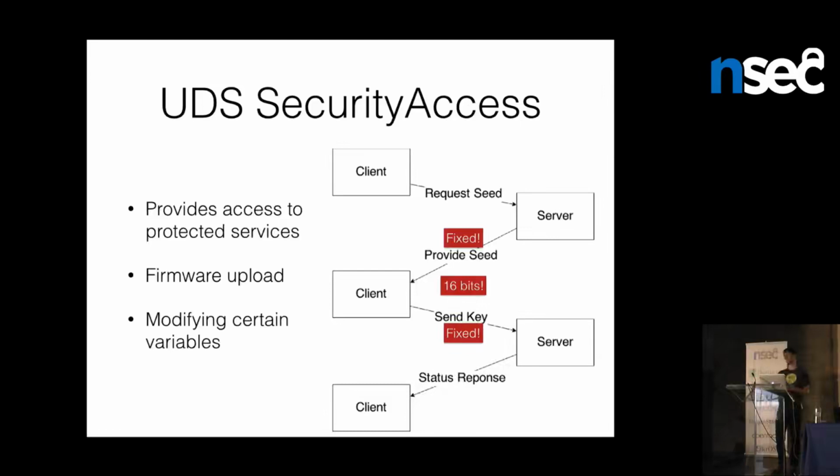Some controllers have a delay from the time you turn the controller on to when you can start requesting this, which, if you read the guidelines, is the recommended thing to do: just wait 1 second to prevent brute forcing. But with 16 bits, you can still do it in a matter of days if you want to take over a specific controller. So it's not great.